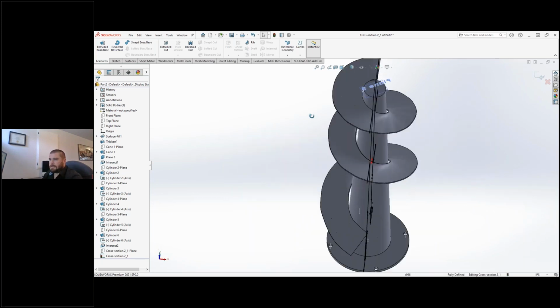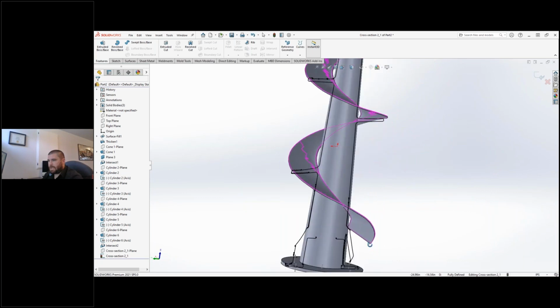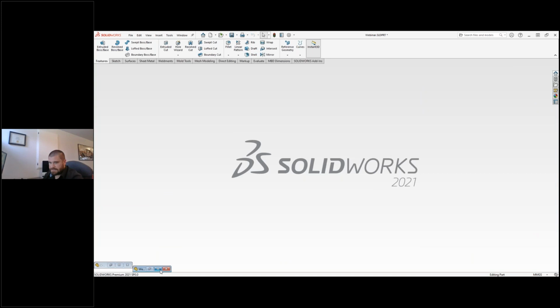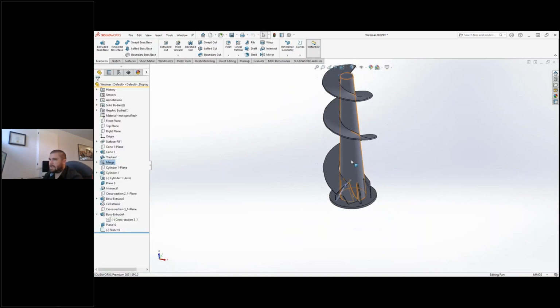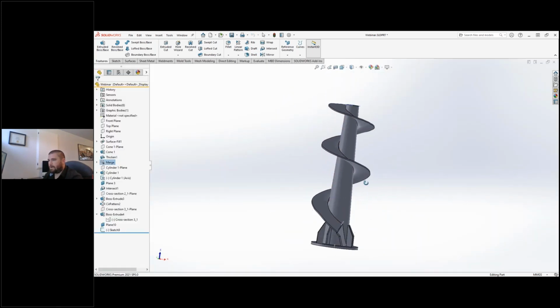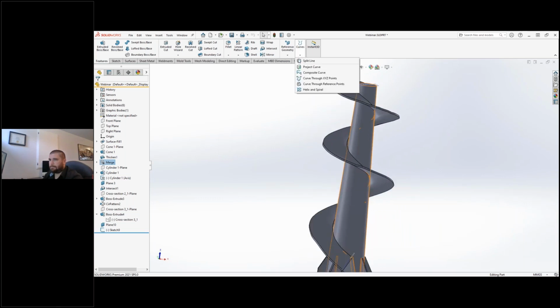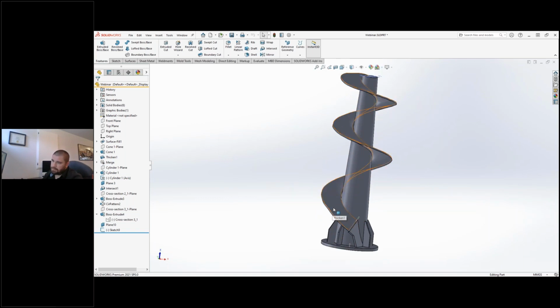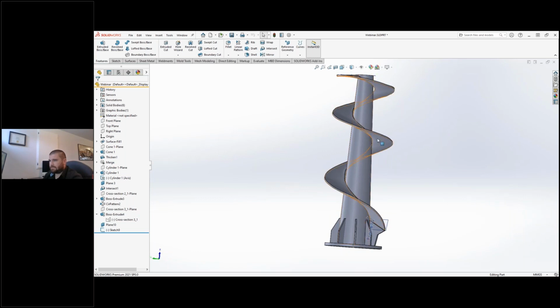Okay. So another way, not the design intent, but sorry, yes, for the design intent instead of the as is reproduction of the part, what I could have done is created a helix and spiral here. What this does is it really creates a perfect spiral. Probably in 2 steps I would have done it here because we could see there's not the same pitch from here to here and here to here. And then that would have created a perfect spiral.